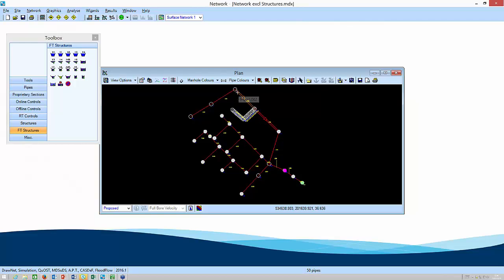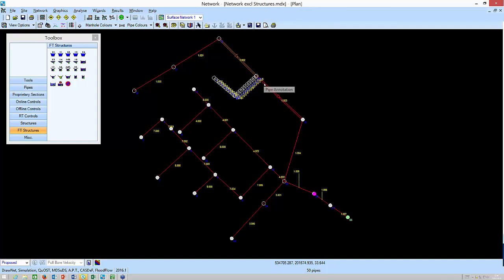Now, how about the ponds? So we're replacing all of these traditional drainage systems with the flow through structures. When we come down towards the pond, I've already got a flow control in place down at this location. But one of the main reasons why people wanted the flow through structures is also to better represent the model. So where everything kind of had to come down to, with a pond, a manhole, we had to drop a pond onto a manhole location. That's no longer the case.